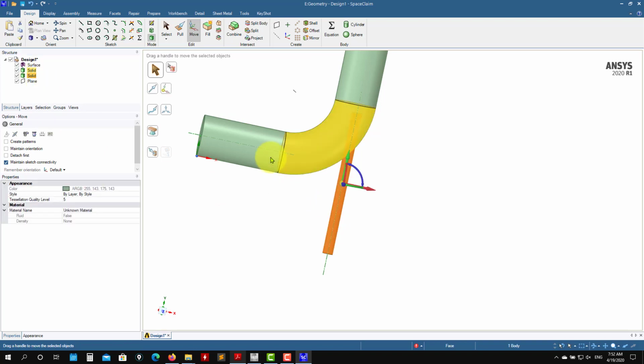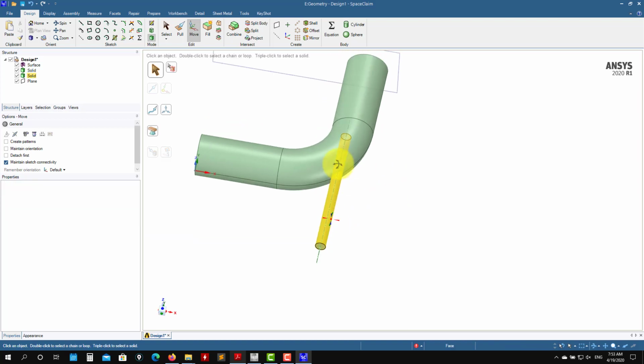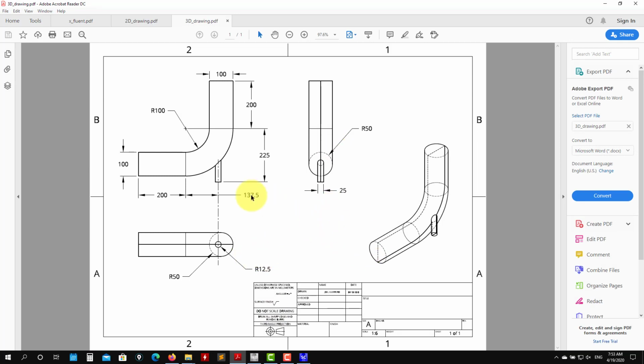I select this one, then select this axis, and here you see you have many options. Select the ruler, and then I want to reference this one or this. Okay, you have it there. That distance was 35. See, it automatically moved. And I can do the same with this one, the bottom. From the bottom, that reference was 255.